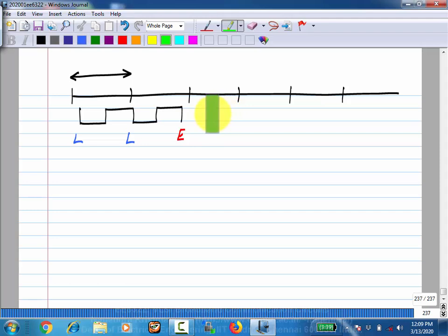It will be at the nominal period, so that means that it will go over there. So here we get a late measurement, here we don't have any measurement, and here you get another late measurement. So that's why it will freeze like that. Is this okay? You can only measure and correct when you have an edge. If you don't have an edge, the phase will remain the same.